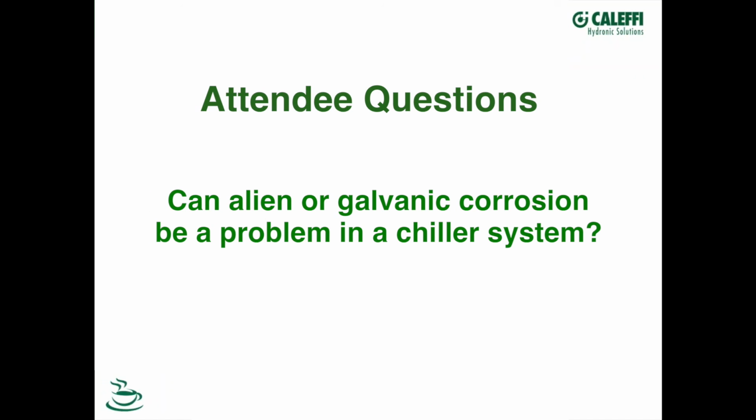I would say yes, especially the galvanic action. As long as that water has electrical conductivity and you've got dissimilar metals, the rate of reaction might be slightly less than it would be in a hot water system, but from a chemical standpoint, everything is in place to create that electrical circuit. So I would say definitely on the galvanic corrosion.